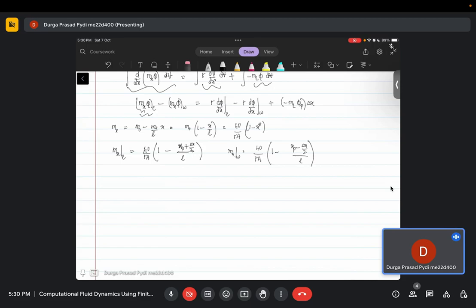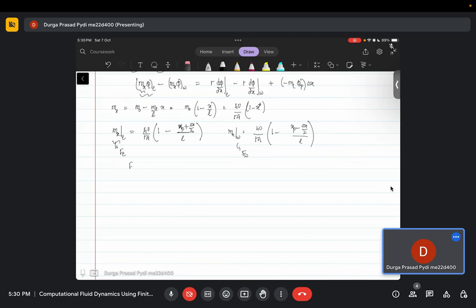The notation that is being used in the lectures is, we call this essentially the mass flux on the east and west faces. So we are denoting it with Fe and this with Fw. So if we write the equations, this will be Fe phi east minus Fw phi west, and for the diffusion terms it's again straightforward. On the east face, we are using linear profile assumption, so phi east minus phi p by delta x, and then on the west face it will be minus phi p minus phi west by delta x, and then we have a source term.